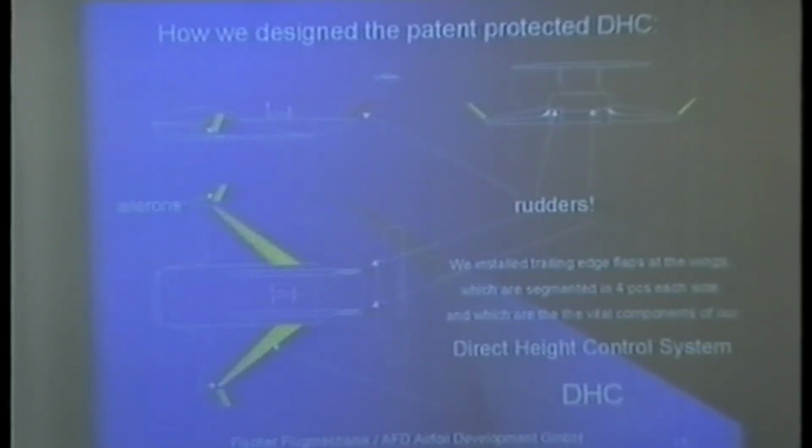And then the next point is we have on the trailing edge the flap, which I have shown to you in the video, and we make it in segments. These are 4 different segments only. And these flaps are sitting on one tube. How it works. These are 4 segments. I will show you why later on. And we can control these flaps to increase our lift.